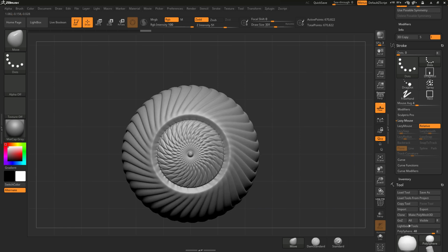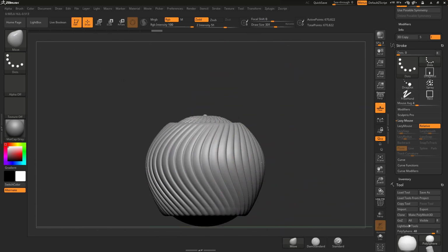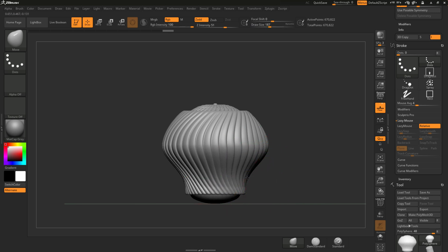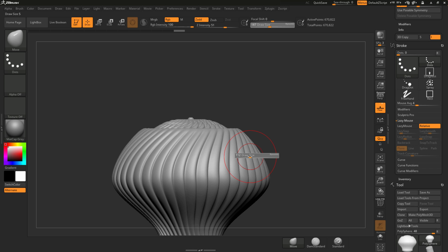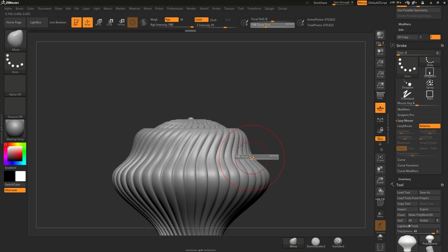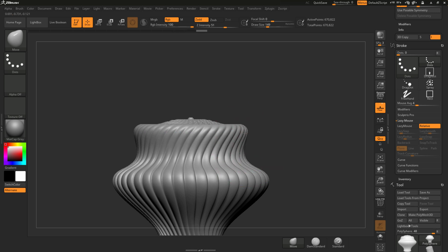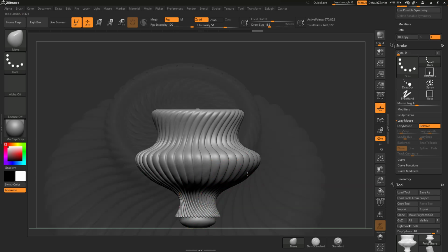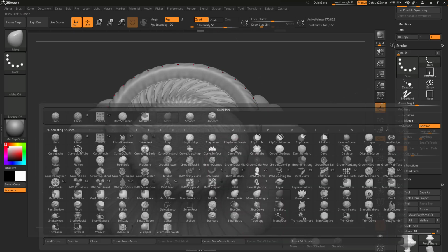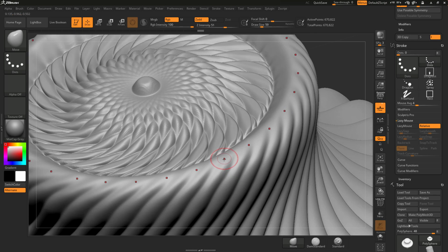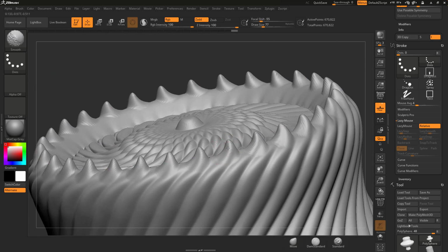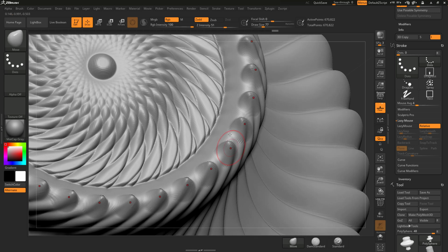And then once we have a nice effect happening here, we can then go in and take a look from the front orthographic. So maybe reducing that move size down to something smaller. And now increasing or decreasing. So if I want to hit a smaller area here, just to shrink this in, decreasing that move brush and starting to pull these shapes out. Grabbing the move brush, we can even go in here with a radial count and begin to sort of pull out additional shapes. So making a slight design change from the original piece.